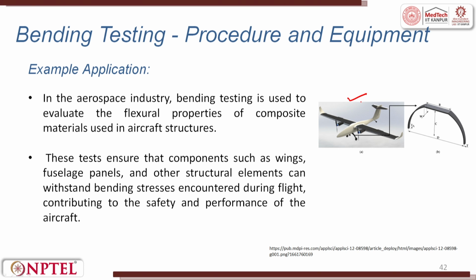So the components or parts of the aircraft such as wings, fuselage panels, and other structural elements can withstand bending stresses encountered during flight. So this contributes to the safety and performance of the aircraft. So the bending test is conducted to replicate a very realistic loading scenario. That is why we use 3-point and 4-point bending fixtures, which exert stress through distinct methods.